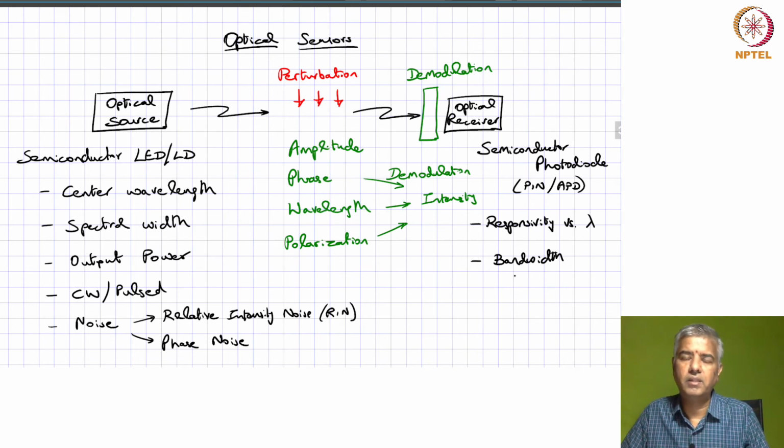of gigahertz. Whereas if you have events like typical strain or temperature events, these tend to be relatively slower. So those are millisecond or even slower than that. So what is the bandwidth you need from your receiver to pick up that sort of slow changes? Well, you may not need much more than a kilohertz of bandwidth for that. Okay, so bandwidth is another important characteristic that you would have to be wary about.